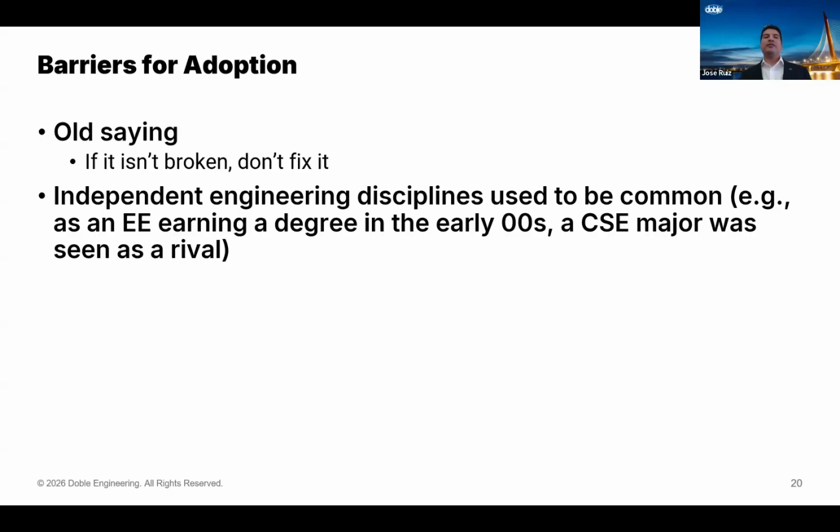So the other challenge that we encounter here is if you are currently working with microprocessor-based relays using hardwire connections, the move from there to virtual protection relays or centralized protection is big because you have to learn first about IEC 61850 and then get used to the new approach of designing all protection in one single device. There are advantages. For example, breaker failure protection. You don't have to worry about coordinating multiple devices because everything is on the same device.